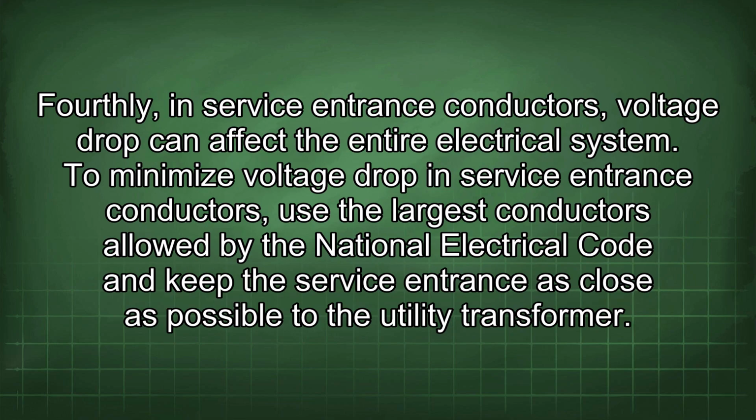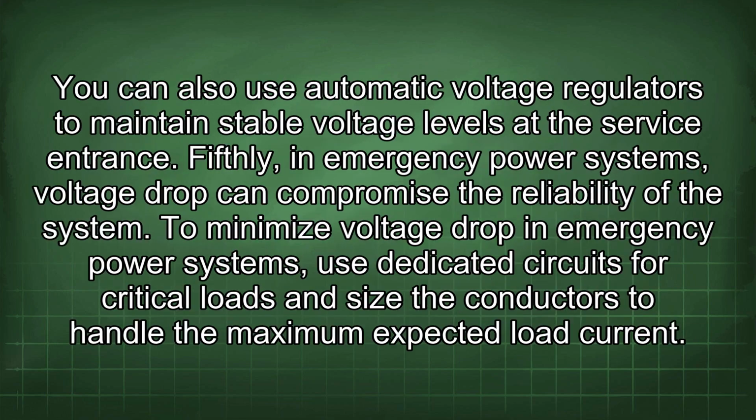Fourthly, in service entrance conductors, voltage drop could affect the entire electrical system. To minimize voltage drop in service entrance conductors, use the largest conductors allowed by the National Electrical Code and keep the service entrance as close as possible to the utility transformer. You can also use automatic voltage regulators to maintain stable voltage levels at the service entrance.